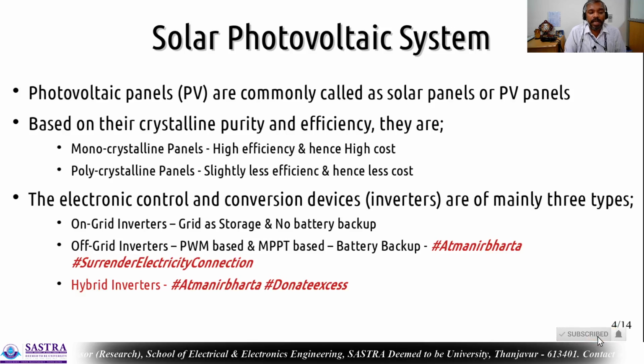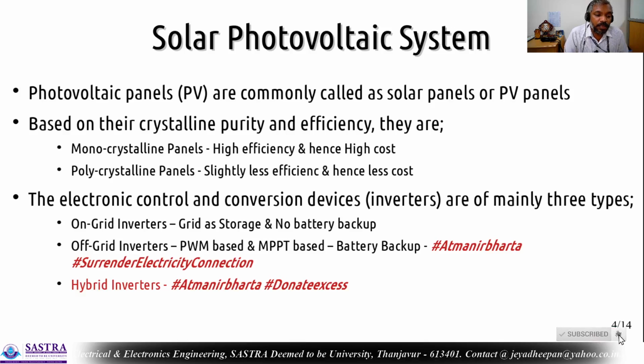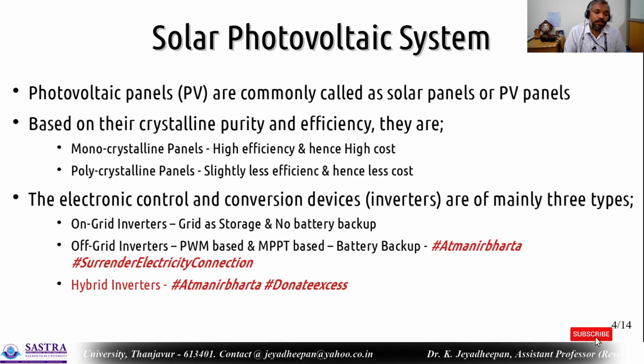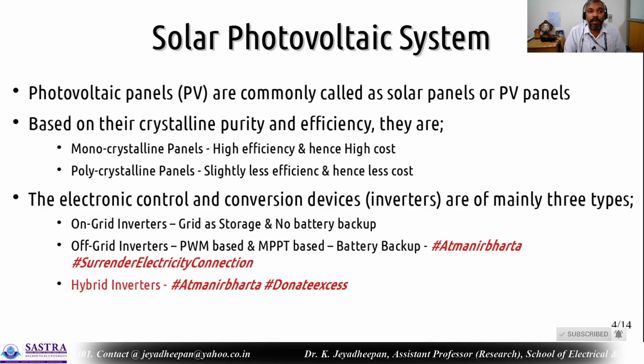The next important thing is the hybrid inverter, right? A hybrid inverter will act as an on-grid and also an off-grid inverter, right? In the daytime, whatever you are producing, you are going to use in your home. The excess energy is going to be exported into the grid, and if needed in the night time, it is going to be called back to the home itself, right? But in hybrid inverters, we are going to have the battery backup also. Since the battery backup is there, and the grid export option is also there, hybrid inverters are somewhat higher in cost, and sometimes it is not advised by some of the electricity boards, okay?